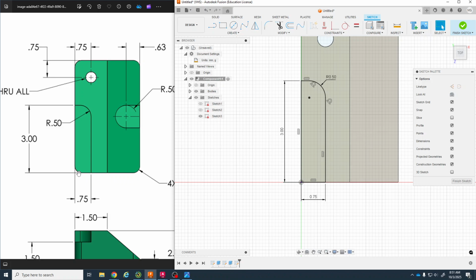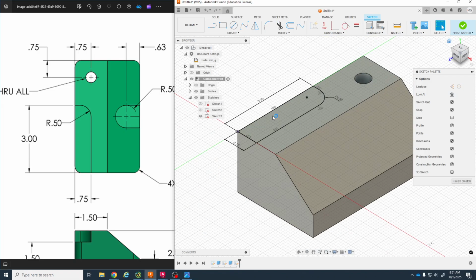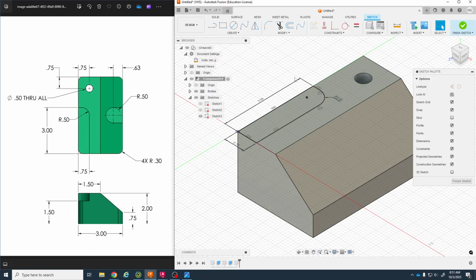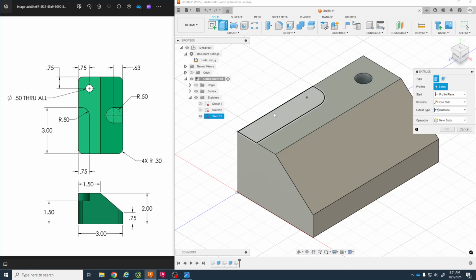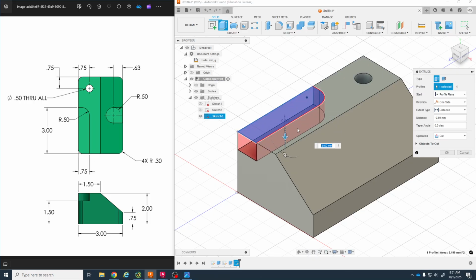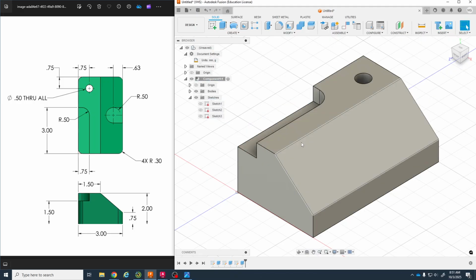And it kind of looks like the shape. There's also a curve down here, but I haven't filleted my object yet, so I should be okay with just this. If I go to the Home tab, if I cut this down, it's going to also cut that, which is, I think, fine. So I said we needed to cut this down 0.5, so I'll click E, click my sketch. My sketch is fully defined via the lock, and then I'll go down -0.5. So I've cut that piece out.